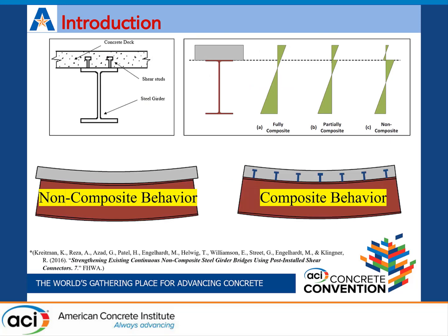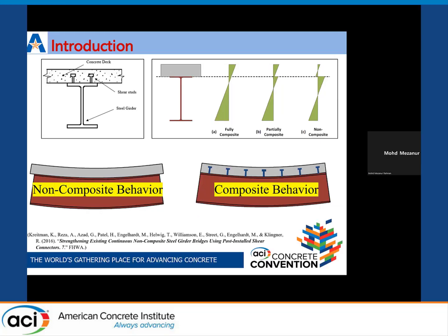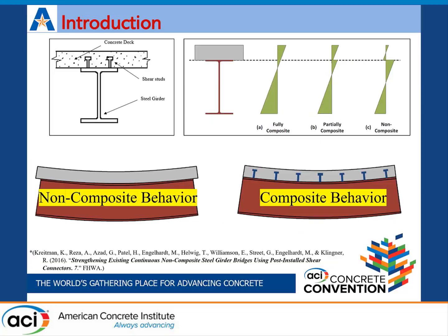Composite-based construction has been practiced since the 1930s. Many older bridges are not designed for composite action. Continuous strain profile can be assumed throughout the section in the case of a composite bridge. On the other hand, in a partially composite bridge, there is a disruption in the strain profile because of fewer shear connectors. There is no chance to develop the fully plastic moment at the interface of the composite beam while it is partially composite.